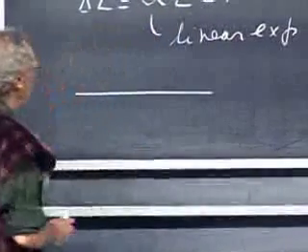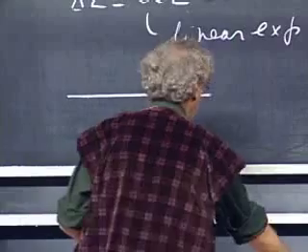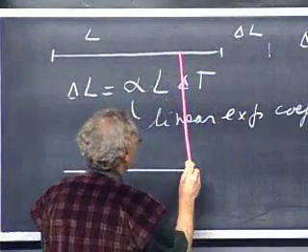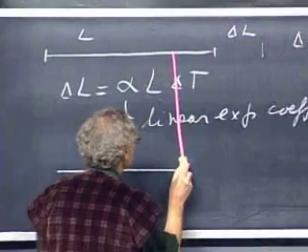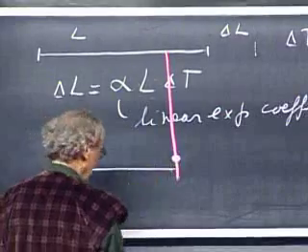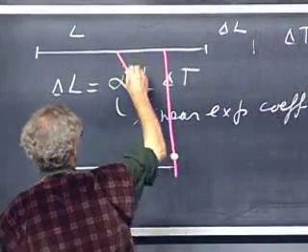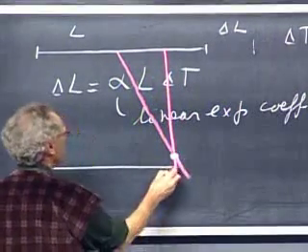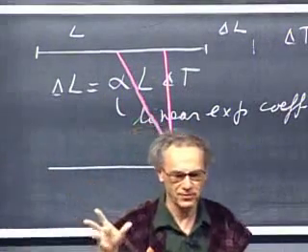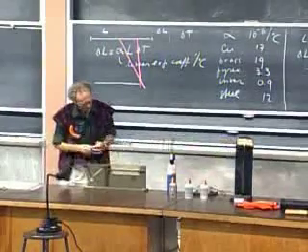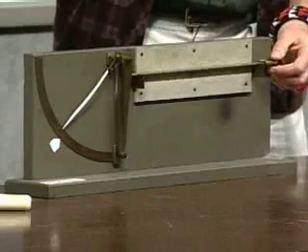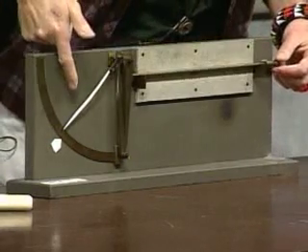If this is the rod, and I put a hand here and pivot that hand here, then it's easy to see that if you push against it here, this hand will go like this. So very little extension here will give you a large extension there. We do it twice, so we have two levels. And that is this arm. I have here a set screw, and I can move the bar in this direction. I'm not making it longer, but I can move it, and you will see what effect it has.